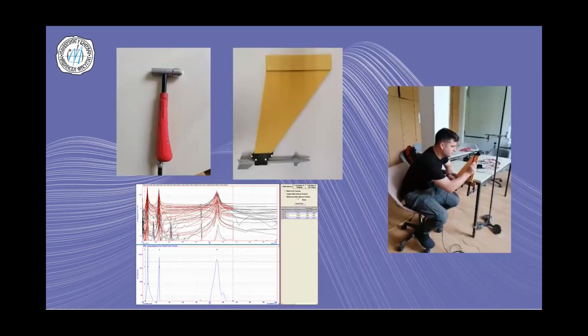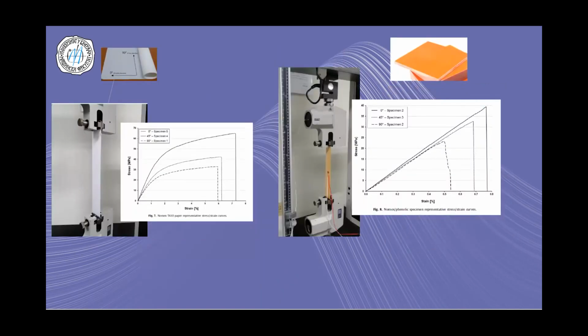These are some of our experiments, starting with dynamic analysis, with modeling certain structures with different approaches, when we actually discovered that these equivalent models are not so precise. Actually, they do not render any kind of result in dynamics. Here you can see the initial test for some specimens of some kind of wings, and the modal analysis, actually the frequency response, the first 3 modes that we are trying to discover.